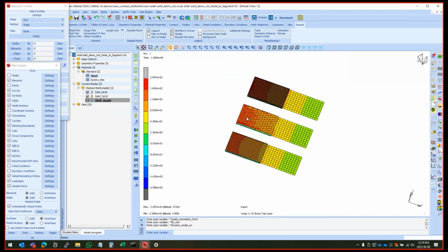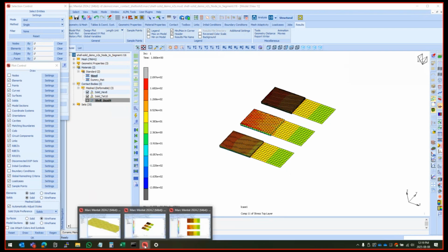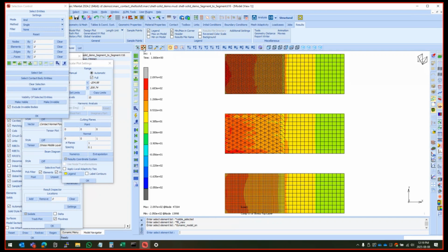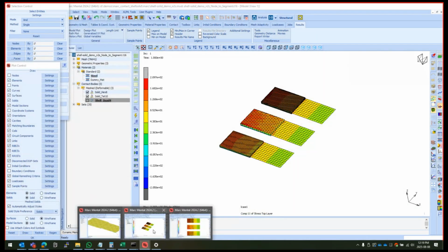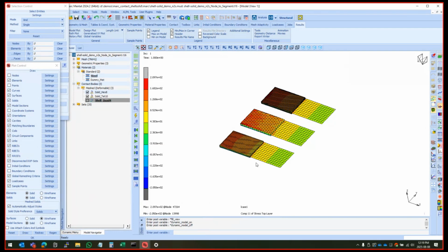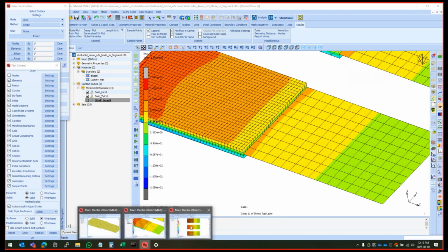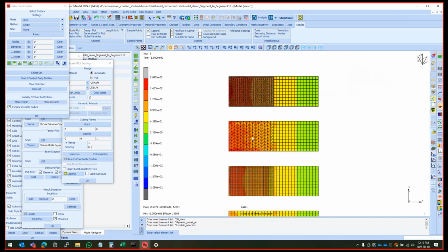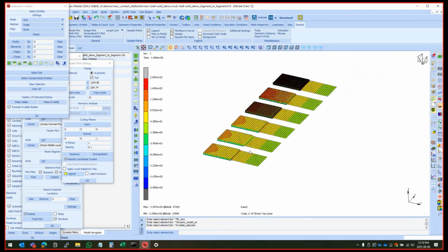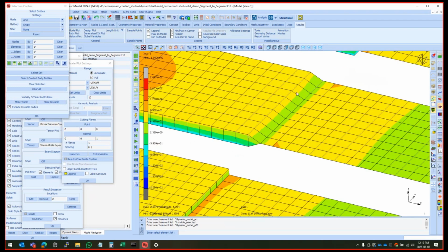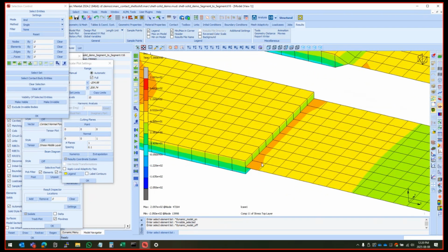Okay, so in summary, what we always face when we have these multiple parts together is I have to in some way connect shells to solids, which is a bit of a pain if you don't use glue contact or some equivalent method. There are simpler methods like, and if I go back to this example again, I plot everything. These first two models where I approximated it using a certain special element that allows connection between shells and solids, or in this case where I've rigidly connected them,